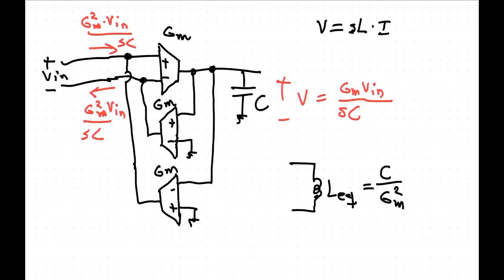Yeah, that's very handy. Now, if we have that, there's two ways we can make active filters, as you might know. Either we can construct them directly from differential equations, or we can substitute a simulated inductor into a sort of passive filter structure, if you like. So either will do. So now we can have complex poles and whatnot that we want in a filter.